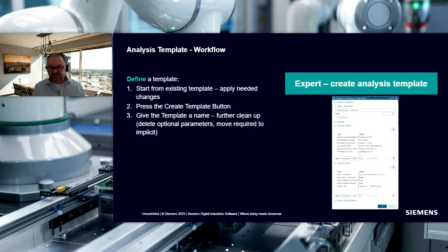You can just take them up here from the list of parameters which may be changed to this small part down here, which is called implicit parameters. So you just have a reduced list of parameters. For example, in this case, you use it for casted structures, and you give it a name, casted structures and stress life.